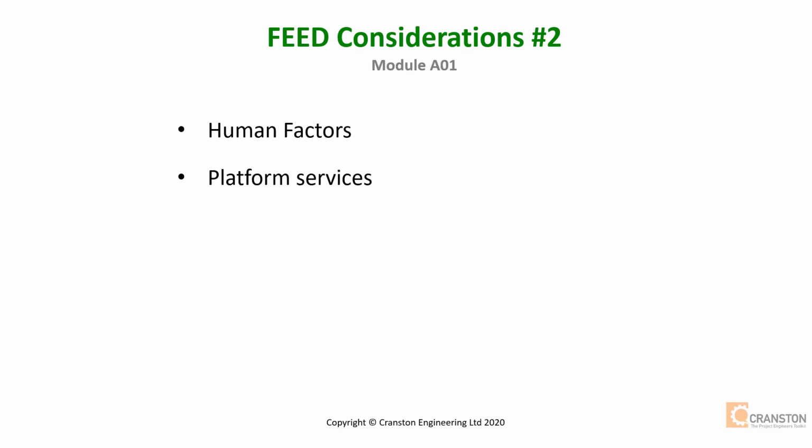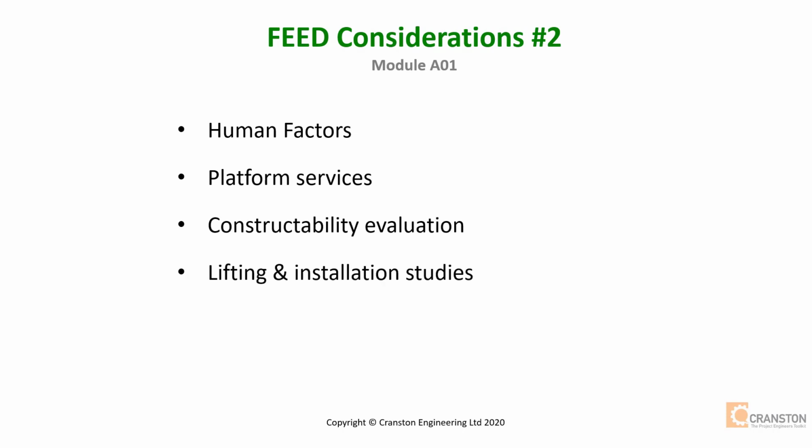Platform services. This will expand on the requirements identified in the conceptual studies and will fully scope what is required for each of the accommodation, piping, electrical and instrumentation systems. Constructability. Enlisting the services of an experienced construction engineer early in FEED will ensure that the design produced can be safely and efficiently constructed. Suggestions on how to simplify and optimise the design from the construction engineer are to be encouraged. Lifting and installation studies.